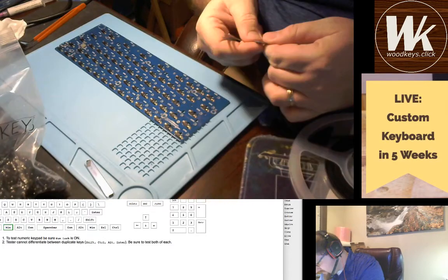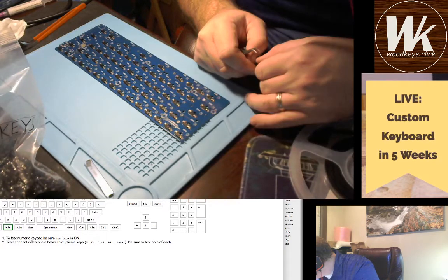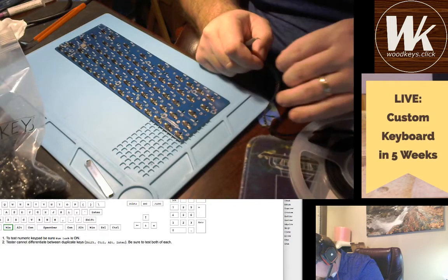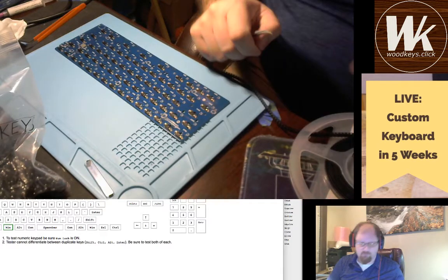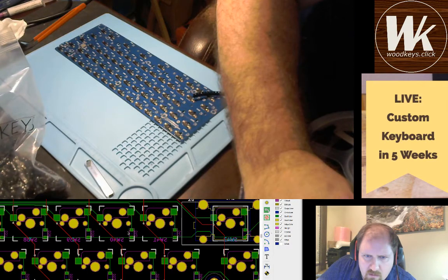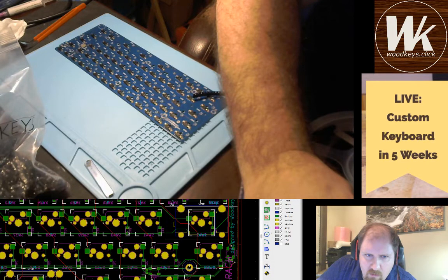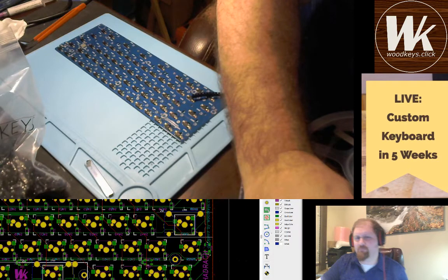So the trick to this is to make sure they're oriented the correct way. And I have this terrible footprint that I forgot to change yet again on the silk screen that makes no indication as to which way is which. So this is why we have KiCAD up, so that I can come in here and see that they are oriented down, facing down, all of them.